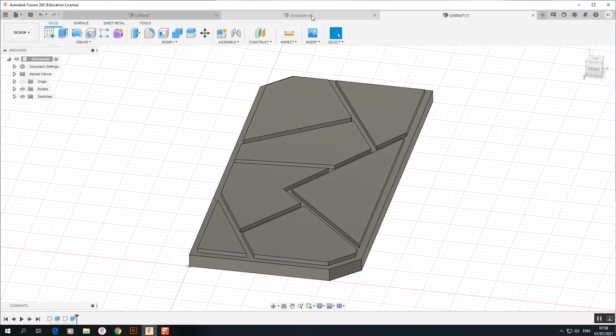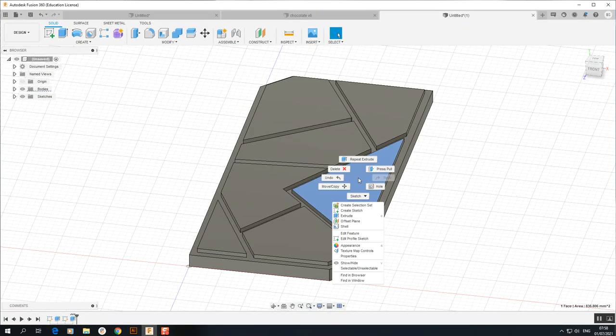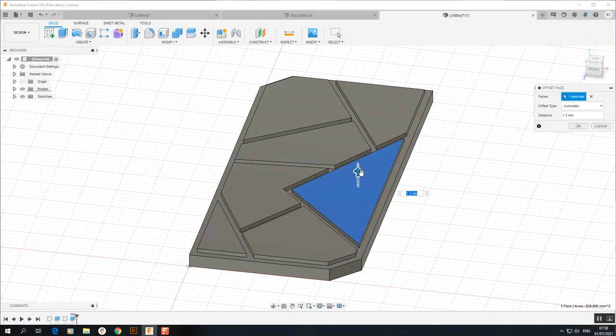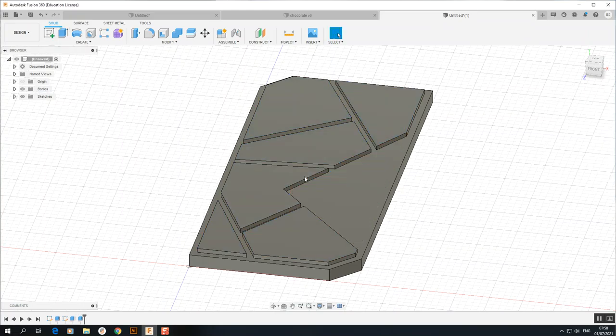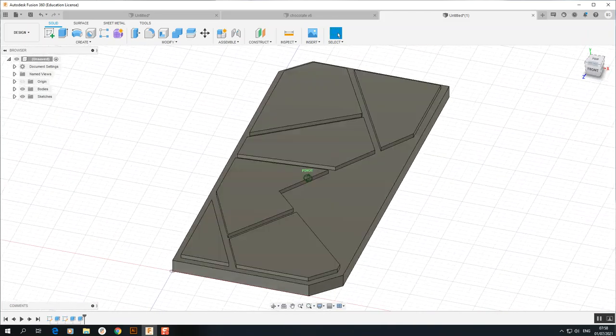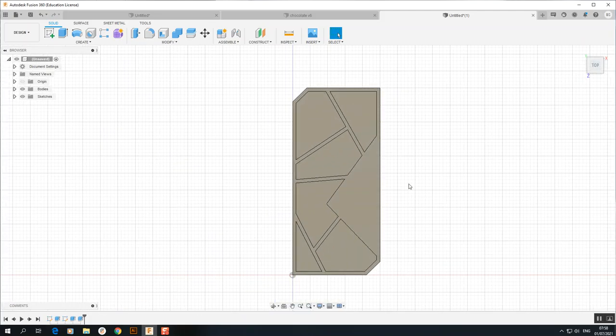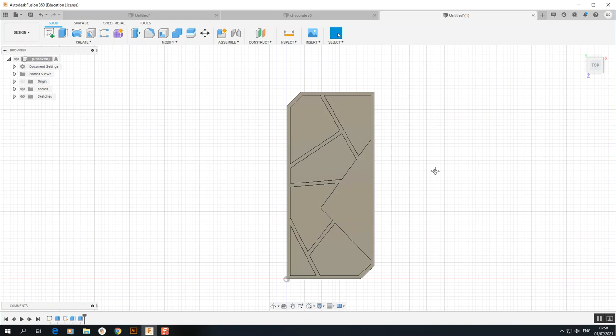And then what I might realise as well is that this part here needs to be pushed in. So I'm just going to push in this again because I don't like it like that. So I'm going to click on the object, click extrude, -1.3, like so, and then it will remove it because obviously it turned red. So this is looking a little bit better. And again, play around with this because the form is completely up to you.